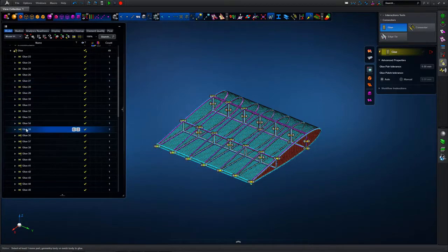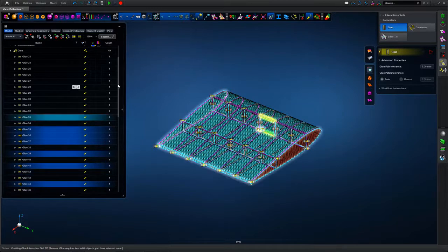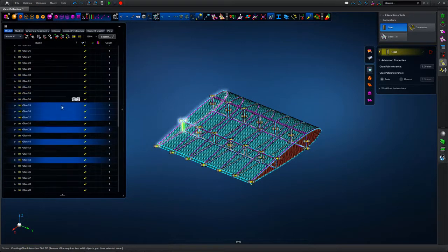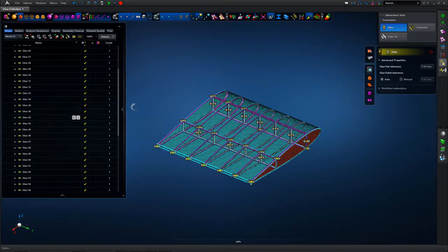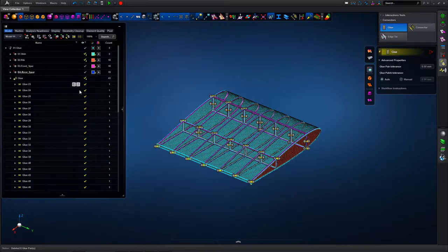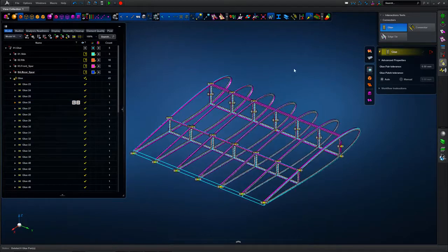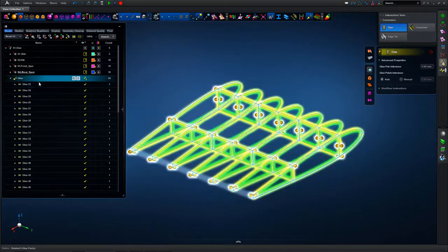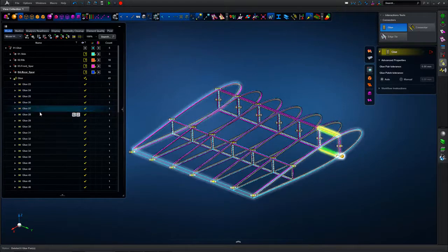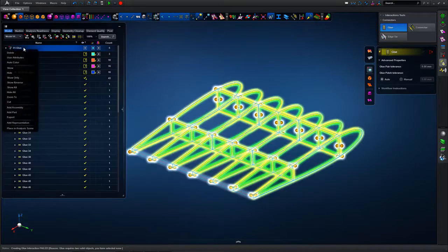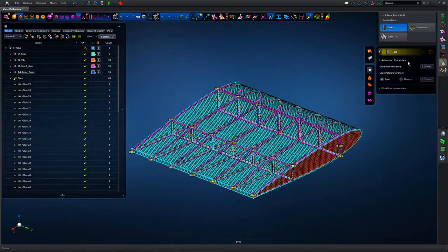Again, the meshless technique. So there are some glue patches which are now redundant based on the legacy layout, or legacy topology, if you like, with the model, so we can just quickly delete those. Apex has flagged them as being redundant, and then just viewing the newly created glue contact pairs, we can see everything is defined as we want it to be.